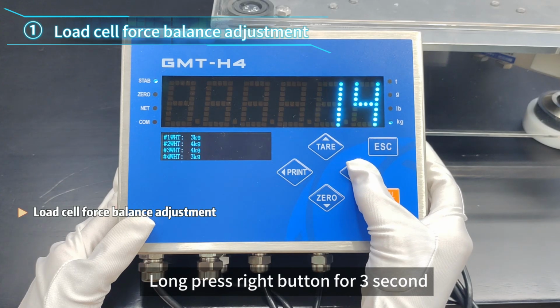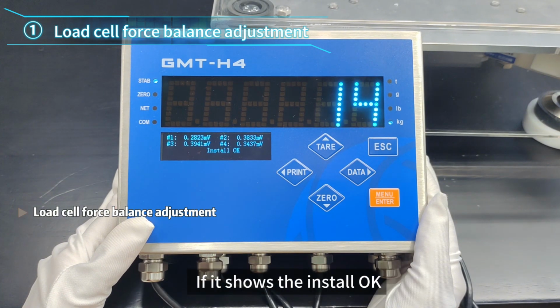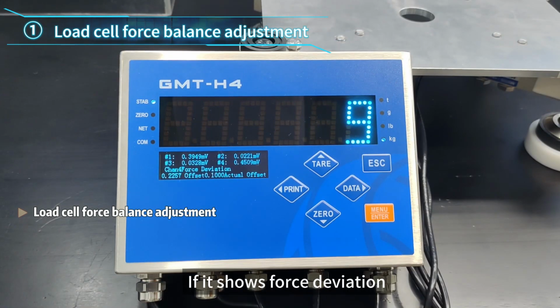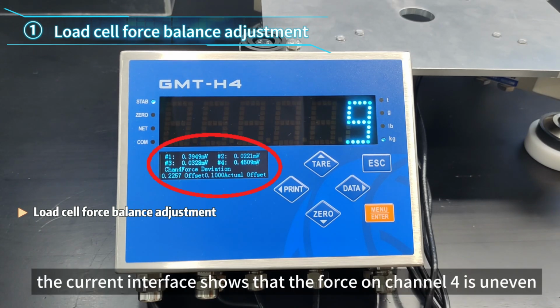Long press the right button for 3 seconds. The OLED screen jumps into the load cell installation debugging interface. If it shows install okay, there is no need for any adjustment. If it shows force deviation, then you need to adjust the load cell force balance. For example, the current interface shows that the force on channel 4 is uneven.